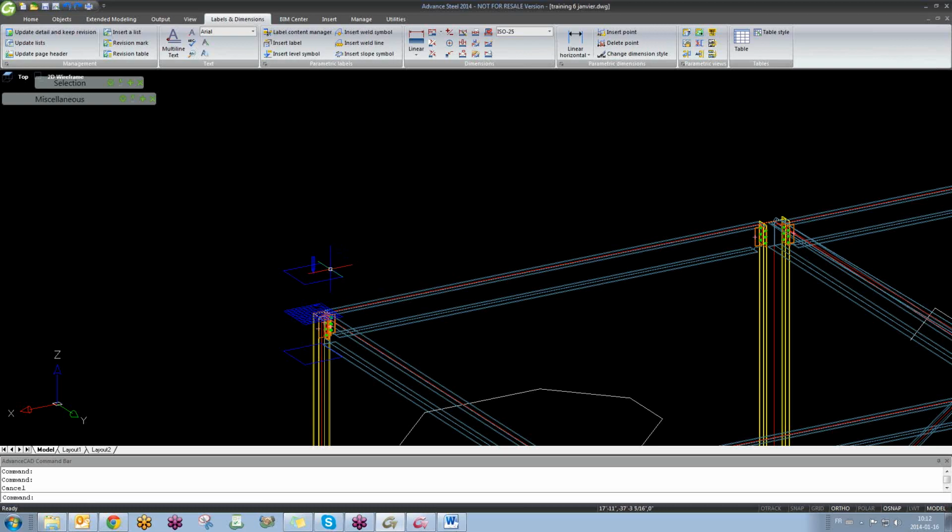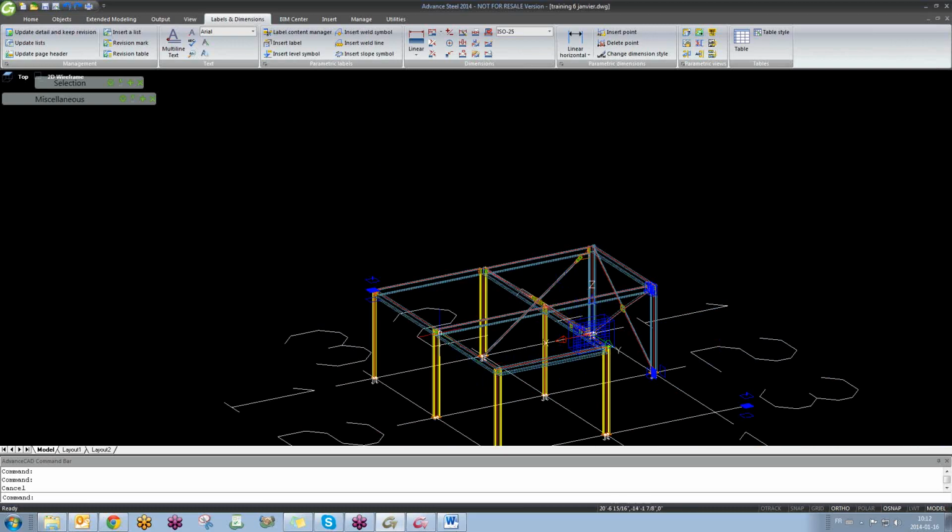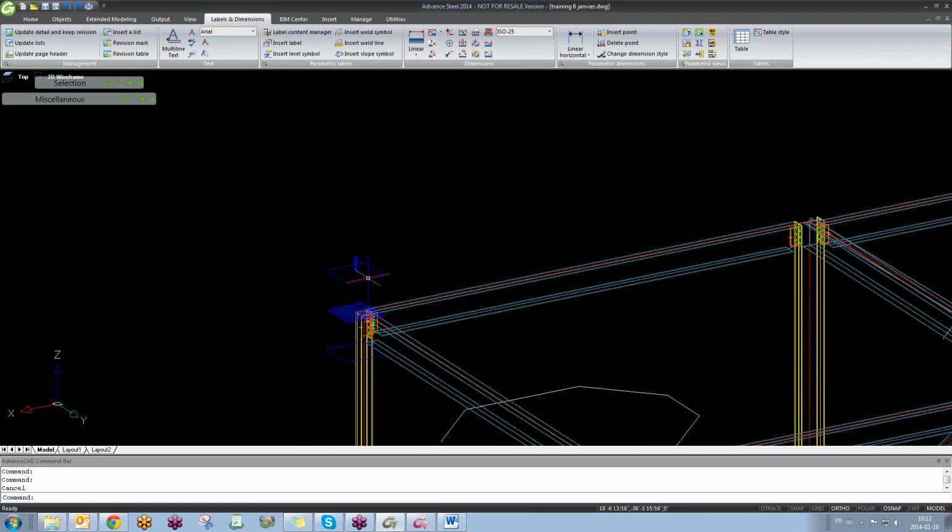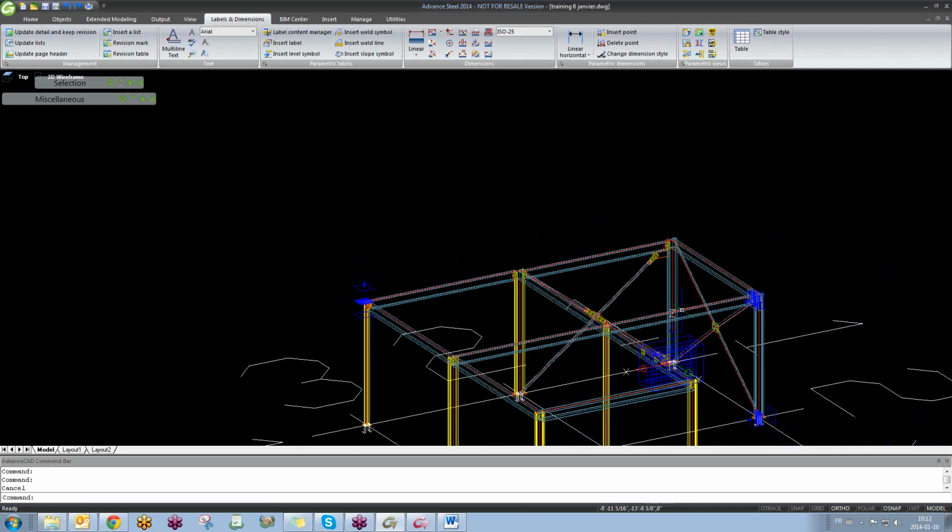Yeah, I understand. What I'm saying is, just make the camera and put it on the sheet. But as I said, put it on the existing drawing, not on a new sheet. Like for example, you have your plan done. While creating your camera, put it on your plan sheet. That will do the job. So you're saying the plan and the section sheet should be on the same page? Exactly.